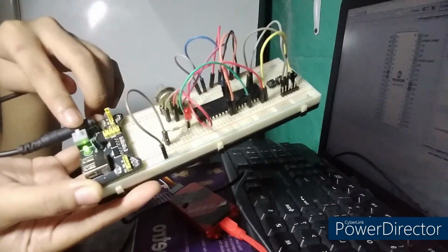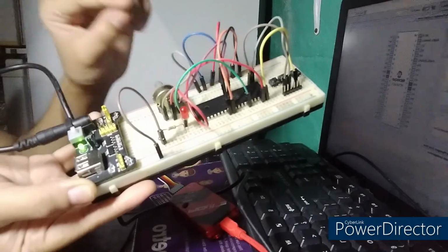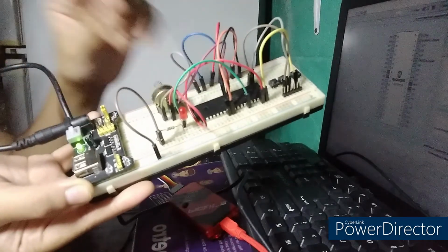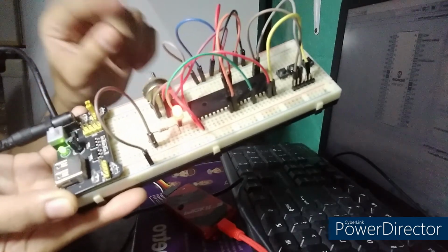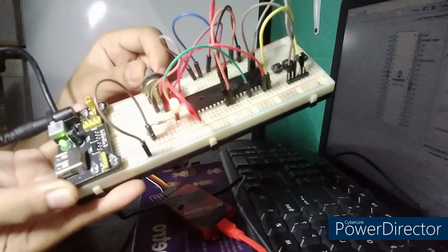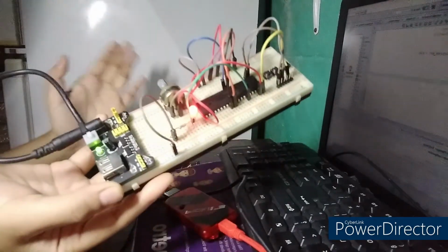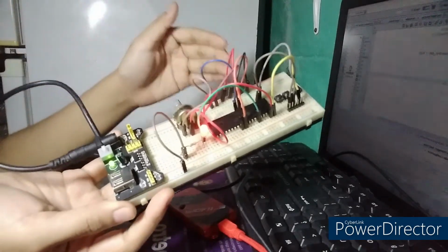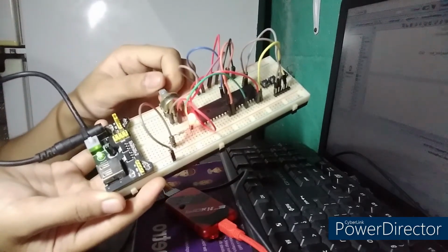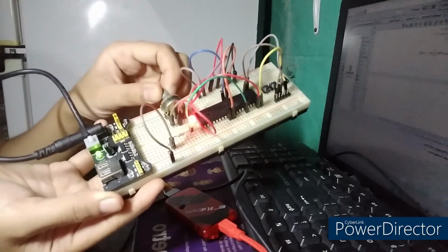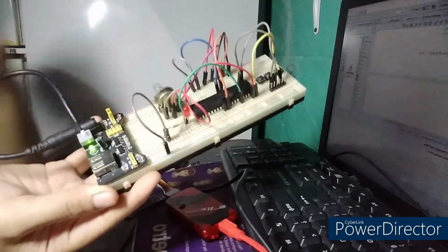Now, our power module is already on, so let's move our potentiometer to the right, just like what we've explained a while ago. If we move it to the right from its center, it should turn on. So let's try it. As you can see, if we move the potentiometer to the right, meaning the value is greater than 512, the LED will turn on, just like what you are seeing here. But if the value from the potentiometer is equal or less than 512, then our LED will be turned off or will be set low.